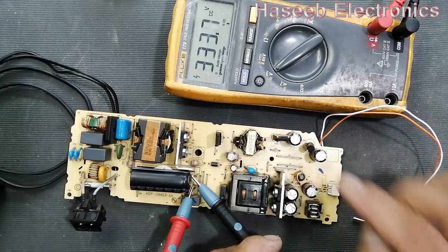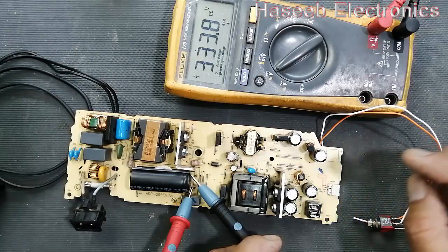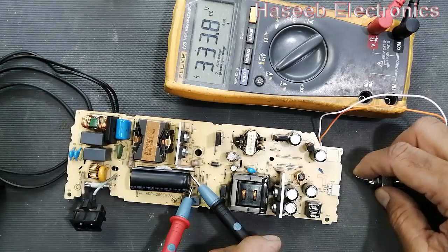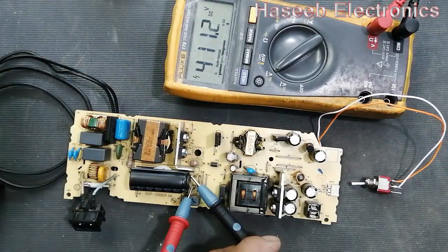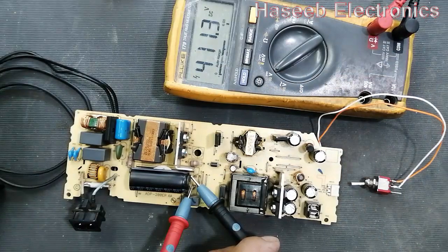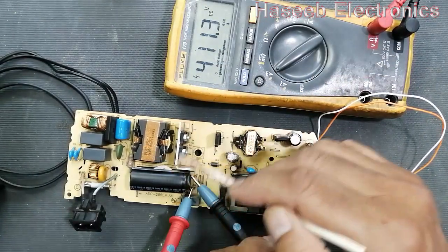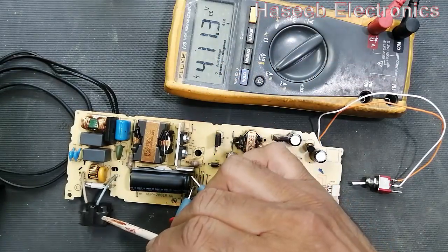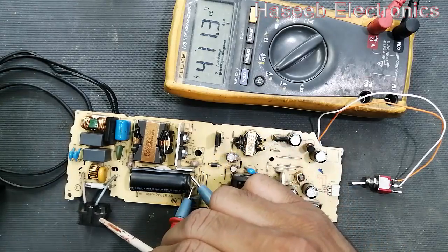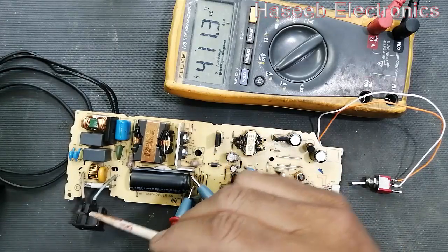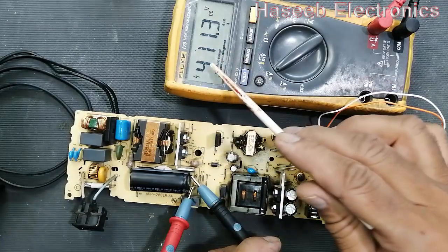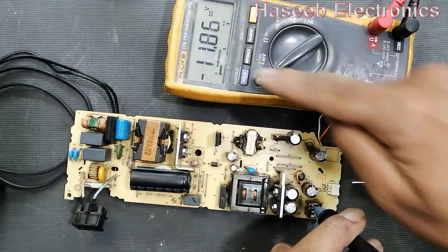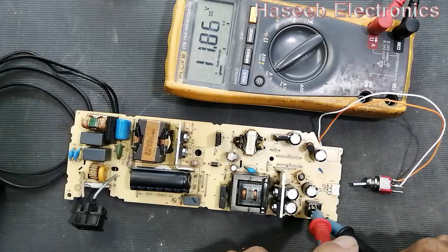When we turn on the power button of our PS4, PlayStation 4, what actually happens is these 5 volts are applied to the AC-DC standby switch. Now I turned on. So this PFC circuit maintained the voltage again at 411 volt, regardless of the input, either it is 85 volt AC, 110 volt, 200, 230, 260 volts. It will maintain the DC level at 411 volts when we need output. 12 volts, it is 11.86 volt.